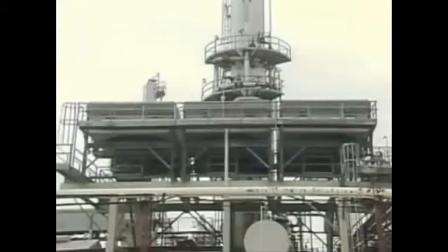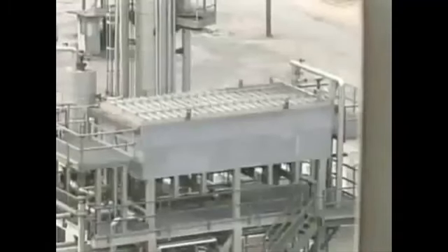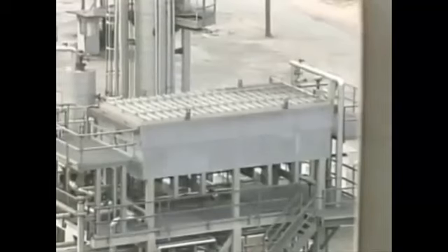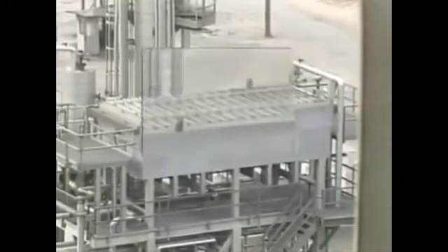In a fin fan condenser, the cooling medium is air. One of the main problems that can reduce the flow of air through a fin fan condenser is a problem with the fans. Also, some fin fan condensers have louvers to help control airflow. In these condensers, airflow can be reduced if the louvers stick in the wrong position. In this topic, we saw how problems with the reflux can affect a distillation system, and we identified some condenser problems.